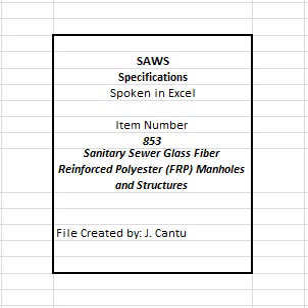6. Contractor shall use a minimum 60-inch/lb torque wrench to tighten the external clamps that secure the test cover to the top of the manhole. 7. The test head shall be inflated in accordance with the manufacturer's recommendations. 8. A vacuum of 10 inches of mercury shall be drawn, and the vacuum pump will be turned off. 9. The test does not begin until after the vacuum pump is off.